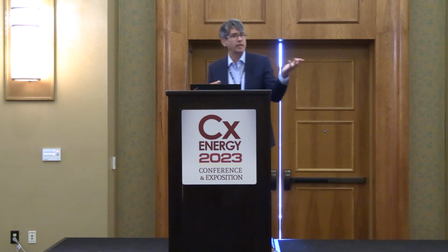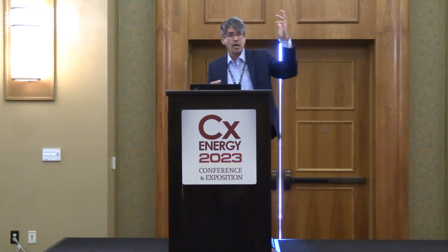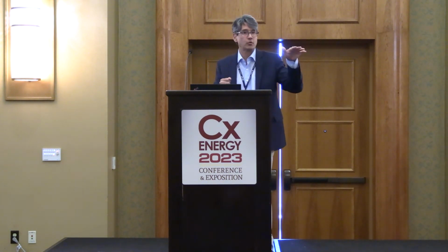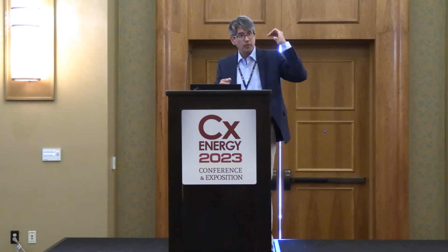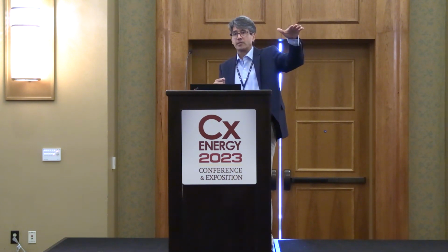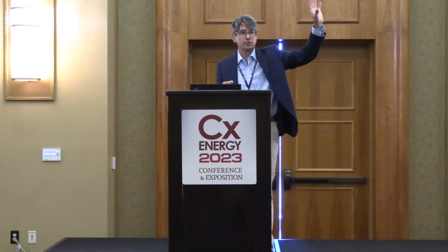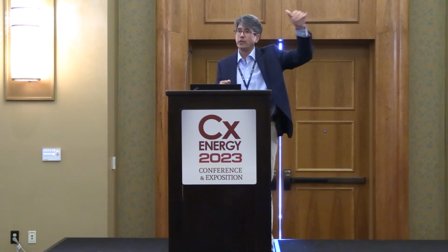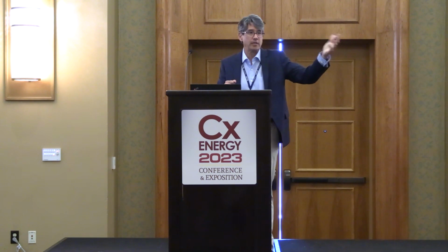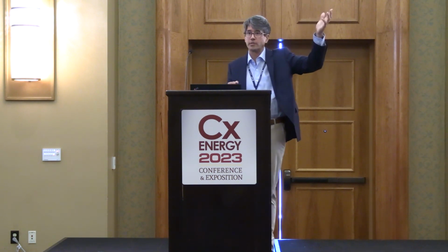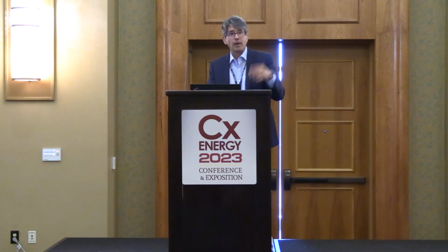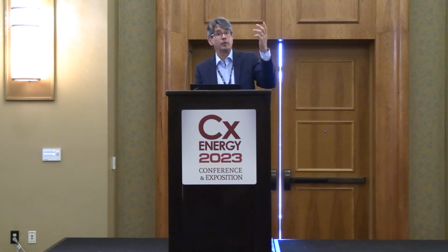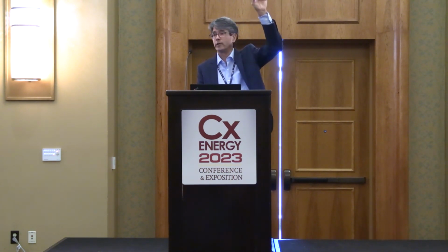Lately, we run a ton of flex space, 20-foot high ceilings. They're going to rent it out to whoever wants to rent it. A guy came in and put his 12-foot drop ceiling in. The owner of the building said, hey, I want all this ductwork up tight to the structure so that if we lease out to somebody in the future and change the space, I don't have to move my ductwork. Go in there, pop a ceiling tile to get to a balancing damper 12 foot high? Oh, I've got another 8 to 10 feet to get to the duct. There's no way to get to the duct. There's no way to get to the dampers.